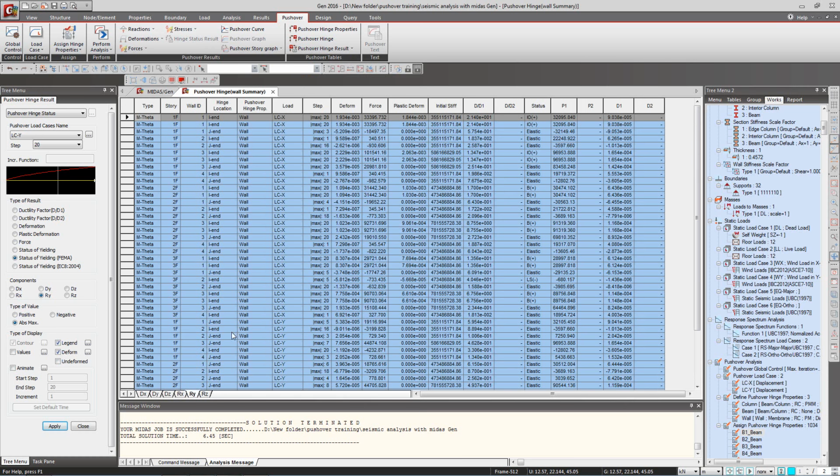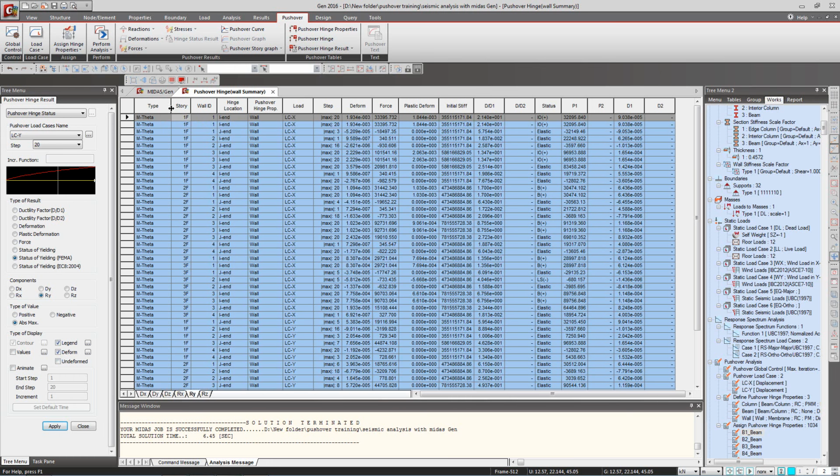We have to check the rotational hinges. Since our shear walls are slender, I have used the rotational hinges. For squat shear walls, we do use the shear hinges. Now as we can see, for different shear walls at top and bottom, these are the situation of the hinges in here. The first floor, I've got the rotational hinge in the shear wall, wall ID 1 at I end.